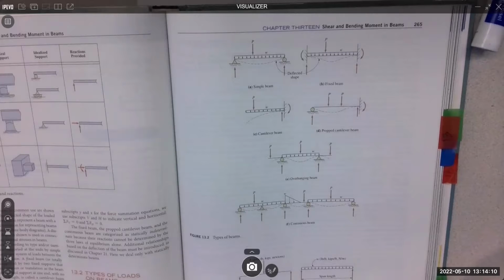So this, I might break into like a triangle, a rectangle, right? 3 shapes. And then concentrate each one of those, this one for this shape, this one for this shape, this one for this shape. Keep it simple. Don't try to deal with the entire load as one geometric shape. That's a bit complicated. But we do concentrate them, and then we can do our sum of forces in the X, sum of forces in the Y, and sum of moments. All right, let's keep going.